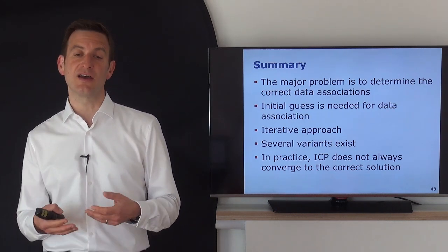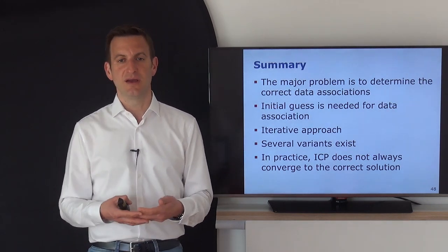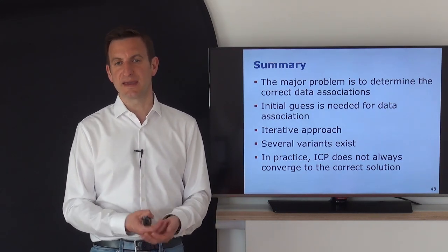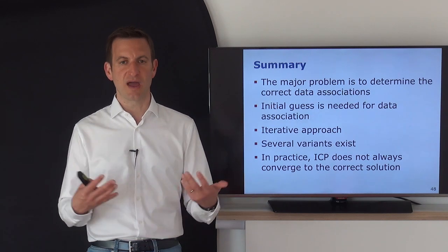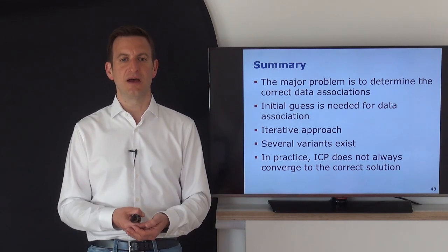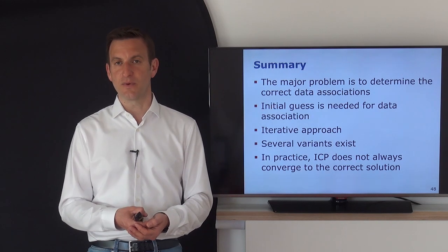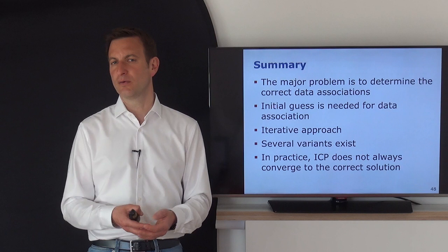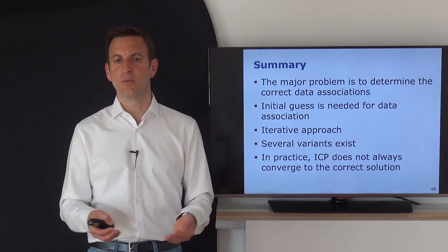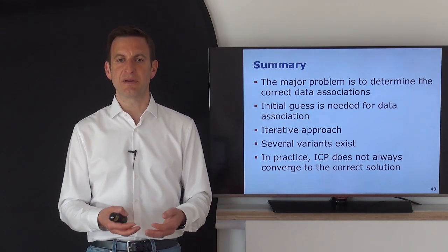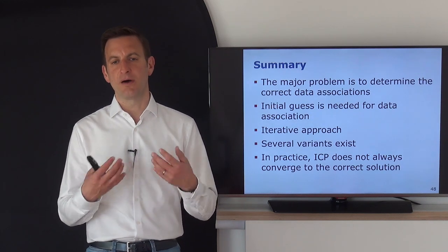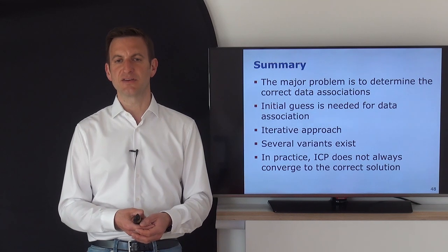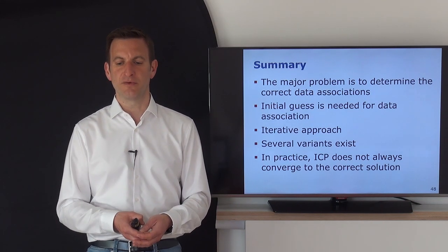In most situations, ICP works surprisingly well, but if you have to align hundreds or thousands of scans, there will be situations in which you make errors, and you need to take those errors into account in your SLAM system, for example, that you have ways for dealing with those outliers. There are different techniques that we will investigate in the remainder of the course, how we can deal with outliers. Again, one idea is RANSAC, a sampling-based approach, or optimizing not for squared errors, but using some robust minimizations or robust kernels in order to perform better here.